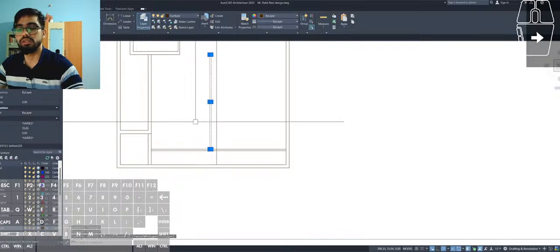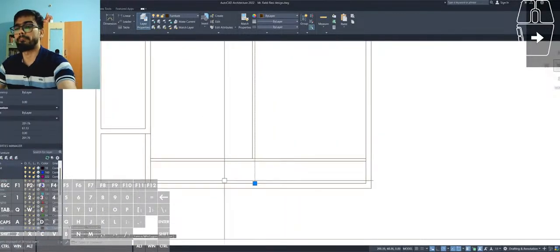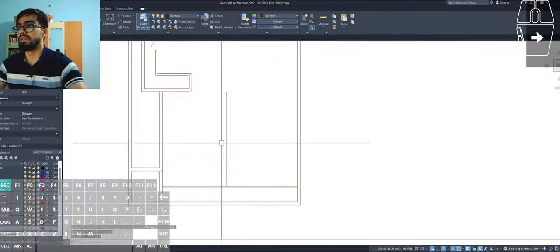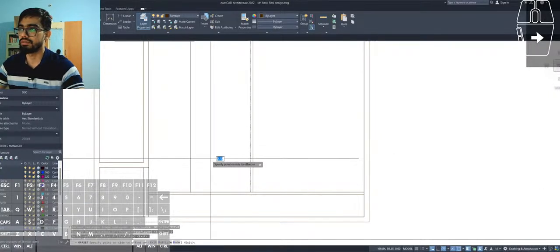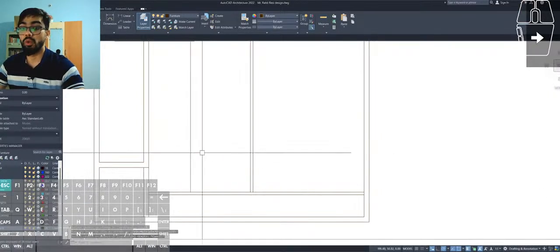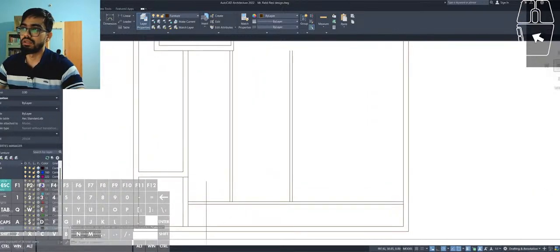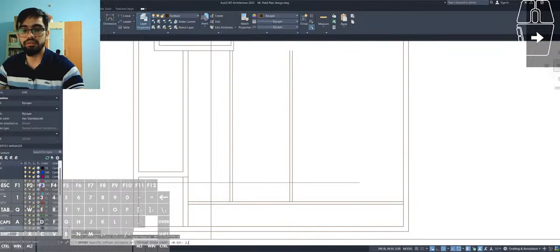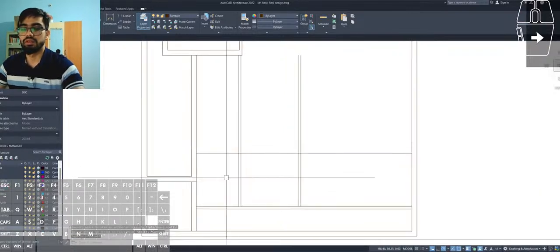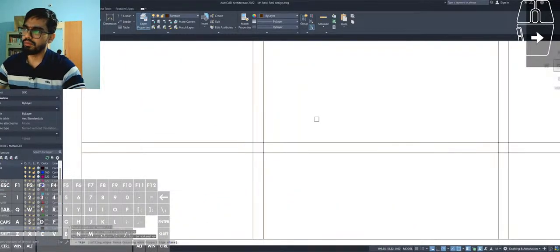So we can use the beam. Perfect. It's more than enough. Offset, I did say 2.4, so let's take it 2.7 for comfortable space. Oh, and there will be the thickness of the wall, which I forgot. So perfect. And then we've got the walk-in closet of 2.4 meters. Set 0.115. Trim.